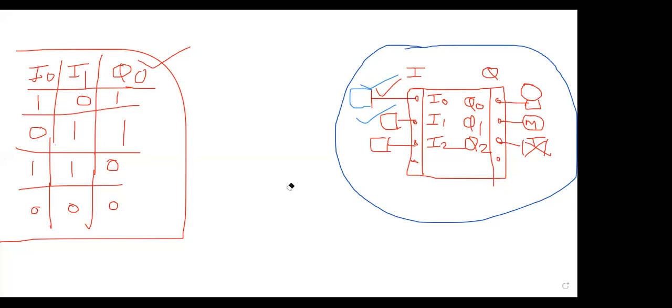But obviously we need to give addresses. Actually, I0, I1 and below that I1, I0. But it should be the opposite contact. You have given the same contact. You see I0 NO, I0 NO. It should be one I0 NO, one I0 NC. Like that. The mistake has been done, you change that. Gil sir, not yet correct. You're trying well.